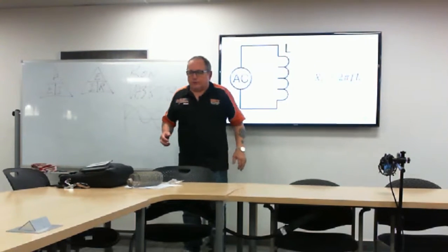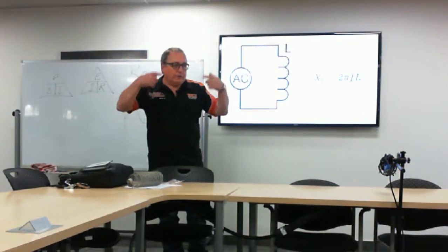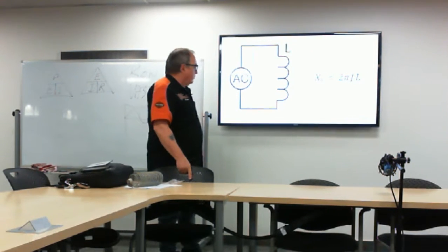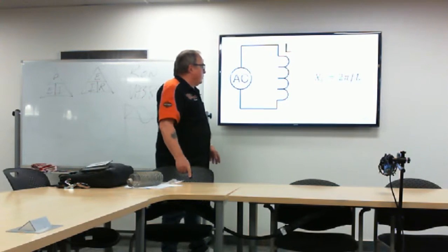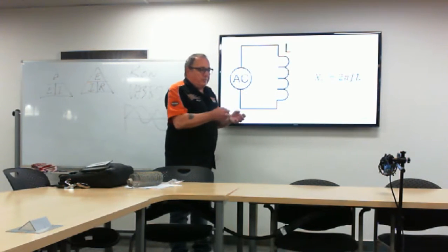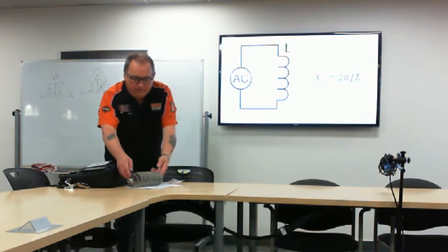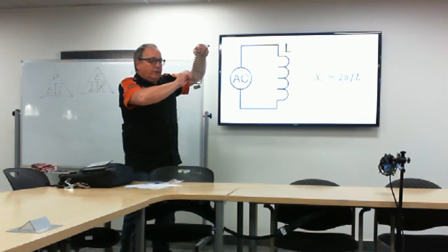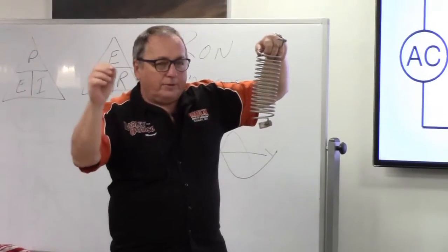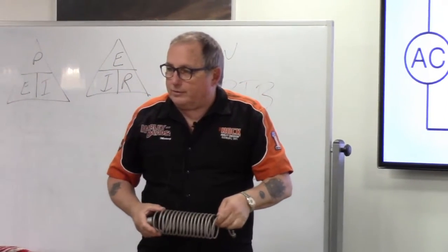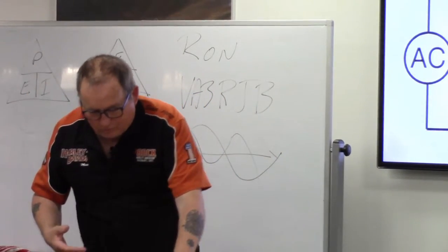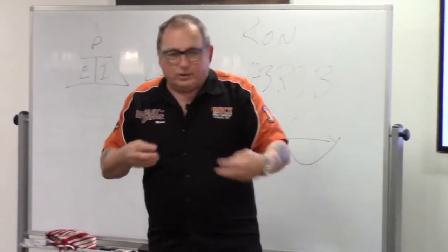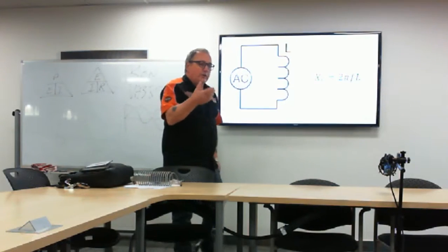That reactance figure is important, and it'll become clearer as we go. So in order to increase the henries in the circuit, you would increase the inductance of the inductor by adding coils. I can change the inductance of this coil by clipping out here, or there. So my input is here, my output is here, or my output is there. You change the number of turns, or you can add more turns, or you can change the coil's core to increase the inductance of the coil.